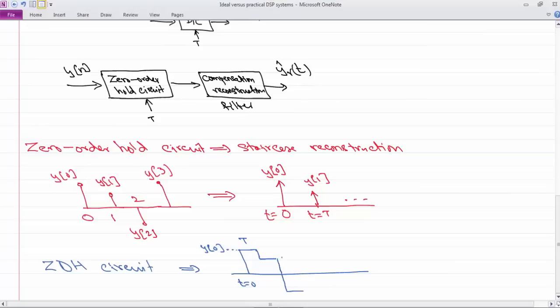So this is now y1. This is y2. Okay. And then it again goes up and holds at y3. So it's like a staircase. You are making a staircase out of your input signal, or of your discrete time sequence. Okay. And of course, you can see that as T gets smaller and smaller, it's just like the integration that you do, that you are getting these staircases, which is going to look more and more like your input signal.